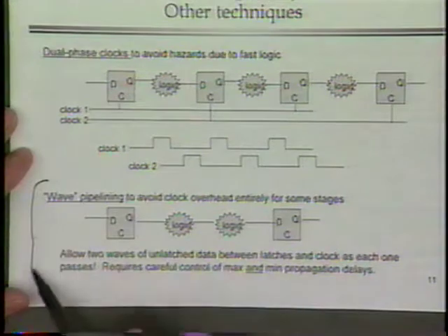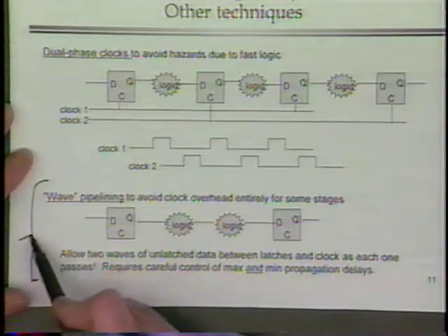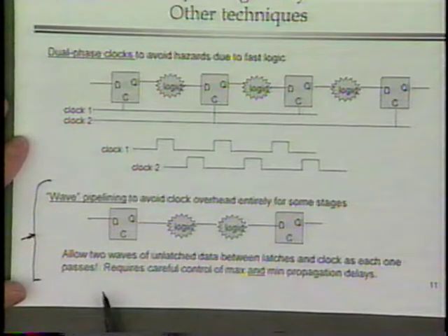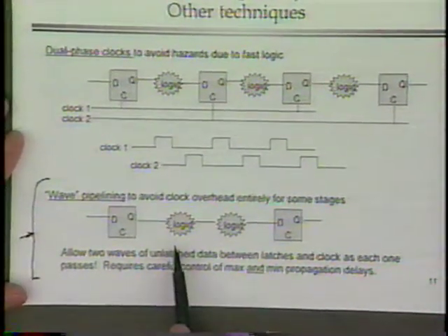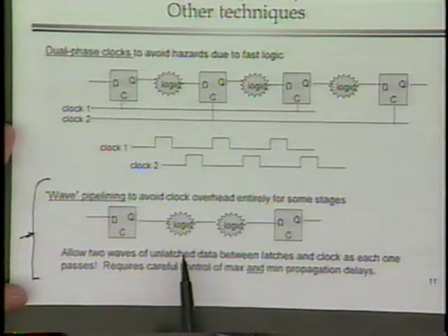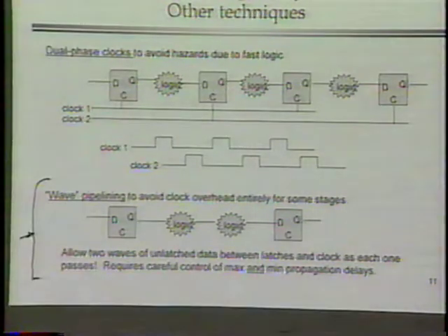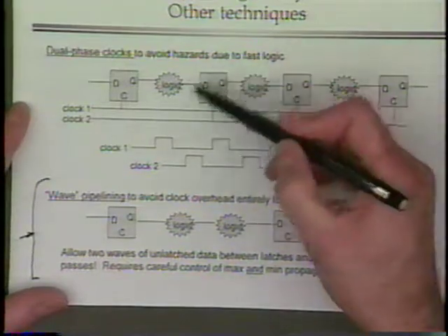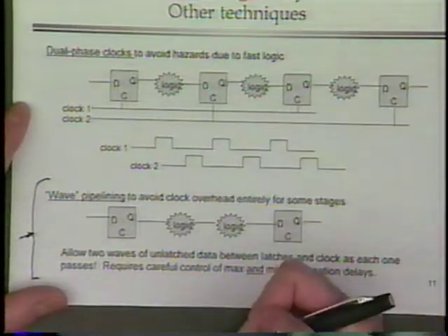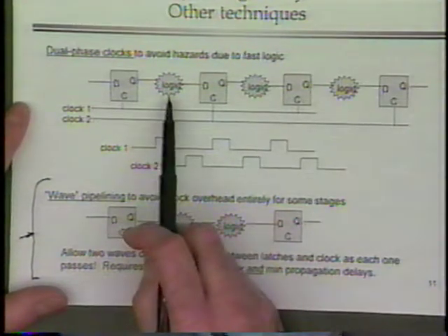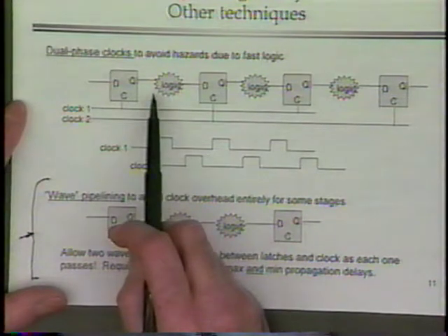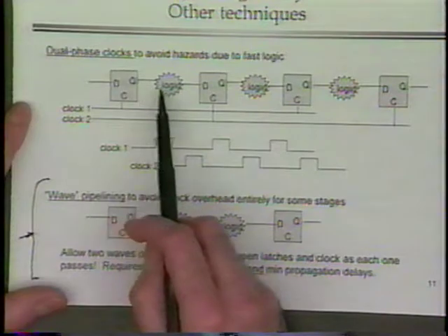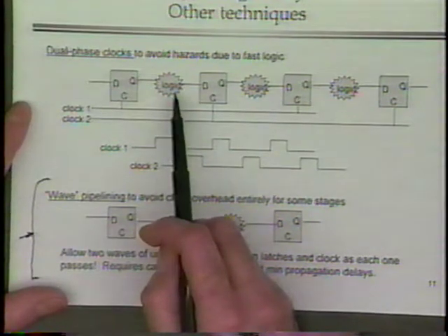One of the more advanced techniques, and this is the last thing I'll say about clocking and advanced pipelining techniques, is that if you are willing to set minimum and maximum delays on the propagation through the logic, one of the things you can think about doing is removing some of these pipeline registers. If it takes a while for data being fed into this bowl of spaghetti to get out to the other end, well, why don't you just wait a while until it's sort of halfway done?